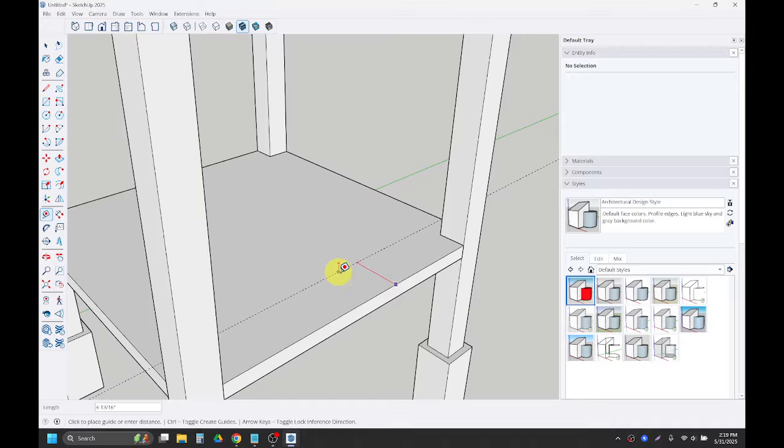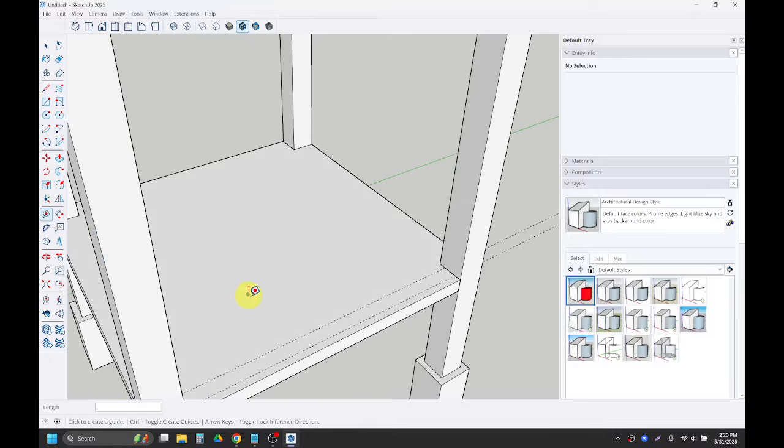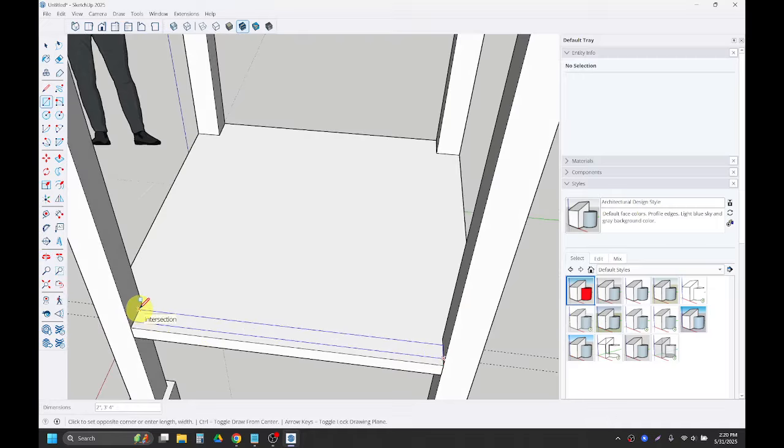And then I'm going to click on the platform edge again, and I'm going to bring in 3 inches. This way, I can use it to make a 2-inch wide rectangle kind of centered on here. So I'll use my rectangle tool, keyboard shortcut R, to go from edge, and let me orbit around to intersection and making sure I'm getting that blue rectangle.